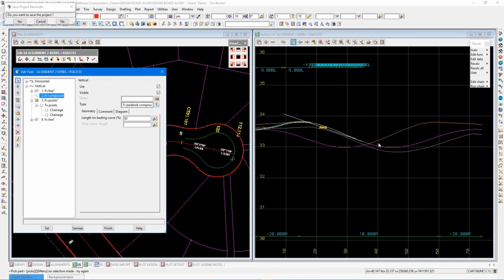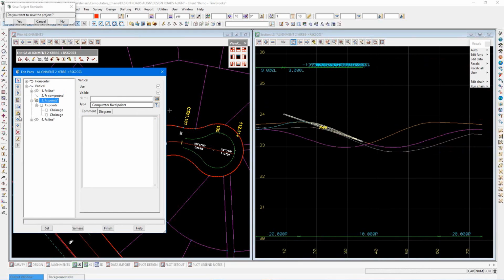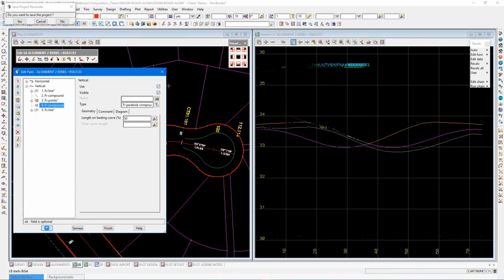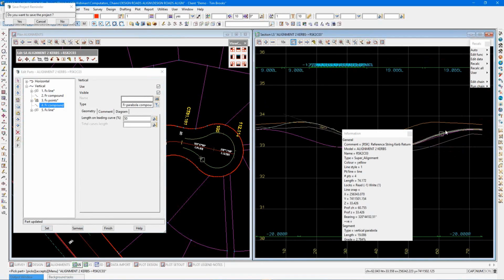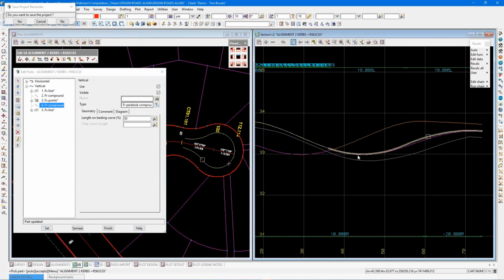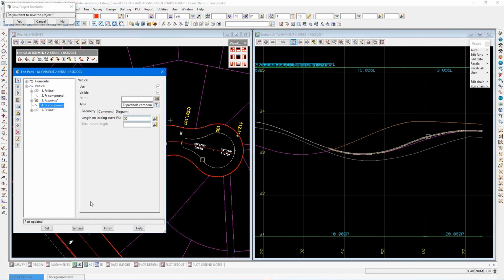And now I just need to finish it off. So again, I could do that with another drape, or perhaps even another compound kerb would simply do that for me. So I'm going to copy this one down, paste it underneath my drape, make sure you turn it on and hit set. And then all I have to do is adjust that percentage until I get my desired result. So in this case, the first kerb needs to be a little bit bigger. So maybe just increase that value a little bit and hit set. And that's looking very close, remembering we are at a distortion of 1:10.